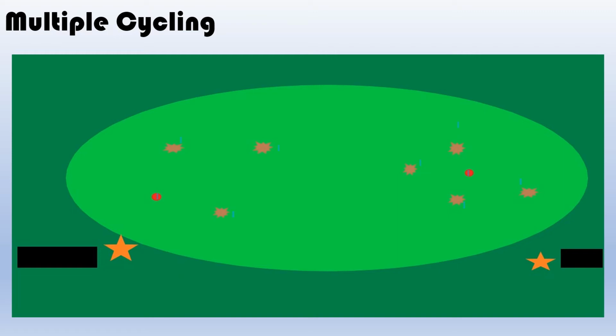So multiple cycling, going along with the strategy of applying light and frequent irrigation, you're going to plug into a quick coupler and apply water to a dry spot, maybe for 2 or 3 minutes. Then you're going to switch to your other dry spot, all within the distance of the same quick coupler. So you'll apply for 2 to 3 minutes here, 2 to 3 minutes here, and then your last in that area, apply some water to this dry spot.